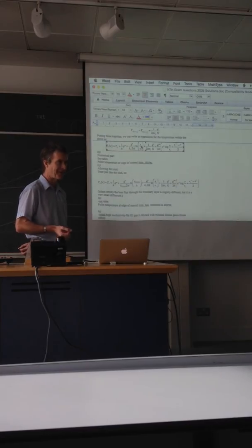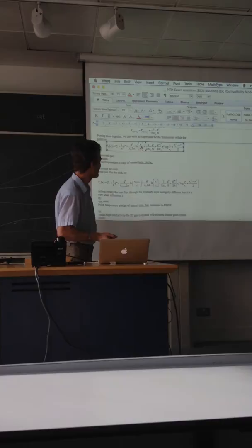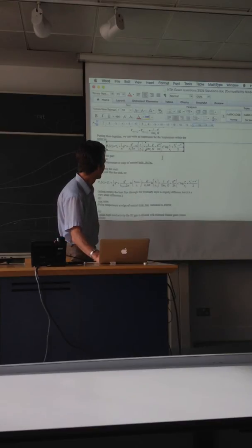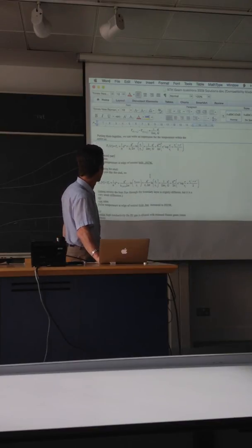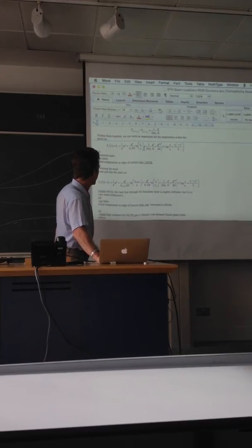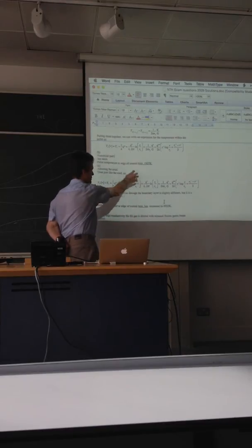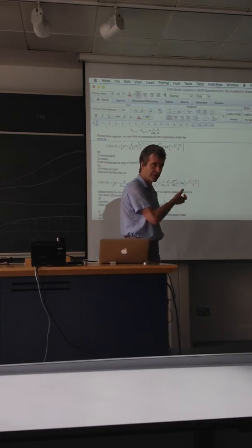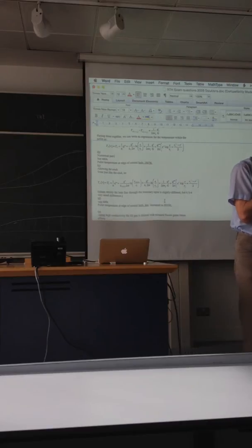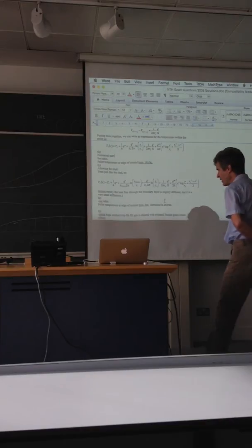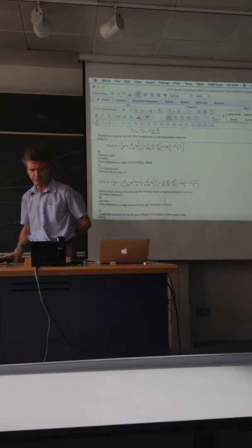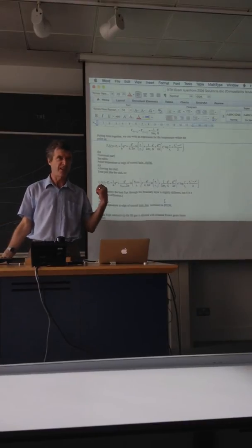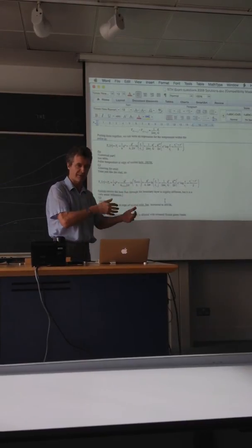Photograph on the screen. It's high tech. So where we had a term for the cladding there, which follows down, we've just got an identical term that pops straight in for the crud. It's just an extra thermal resistance featuring in exactly the same way. So perfectly straightforward. If you understood how the cladding comes into that overall expression, you can just write the answer down: there's an extra layer, it will have exactly the same form.